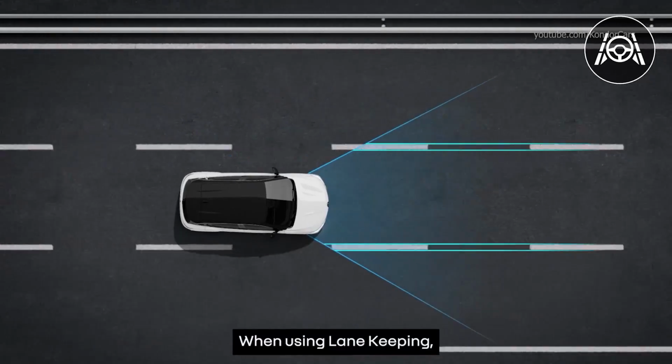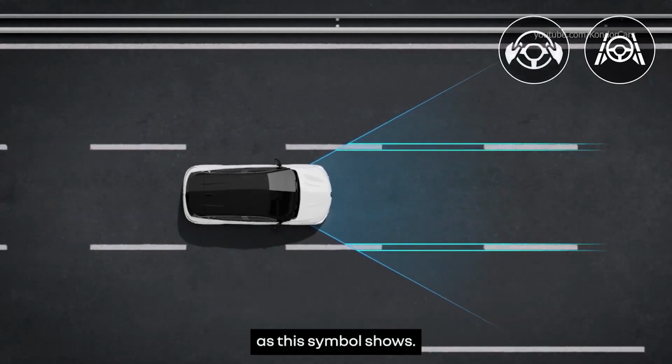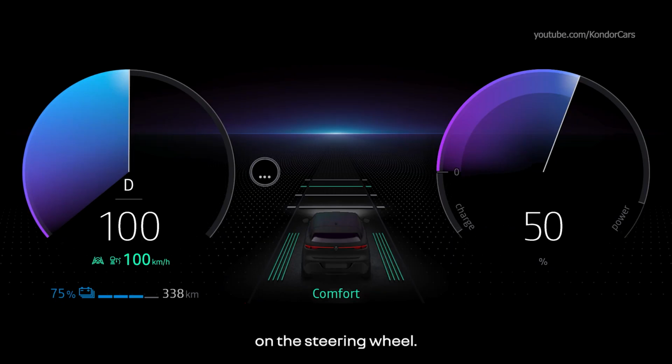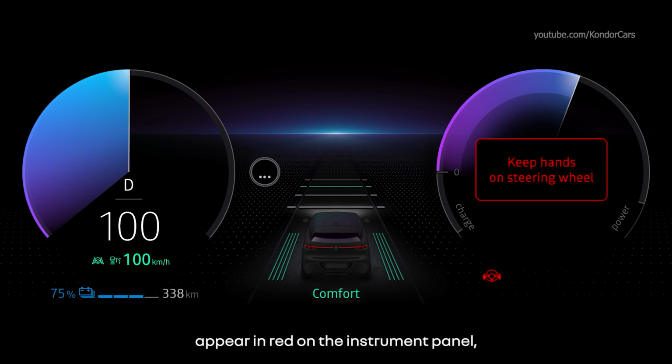When using lane keeping, you must still have your hands on the steering wheel, as this symbol shows. The system warns you if it cannot detect your hands on the steering wheel. After 15 seconds, the message "Keep your hands on the wheel" appears in yellow on the instrument panel. After 30 seconds, the indicator light and message appear in red on the instrument panel, accompanied by an audible signal which gets progressively louder.